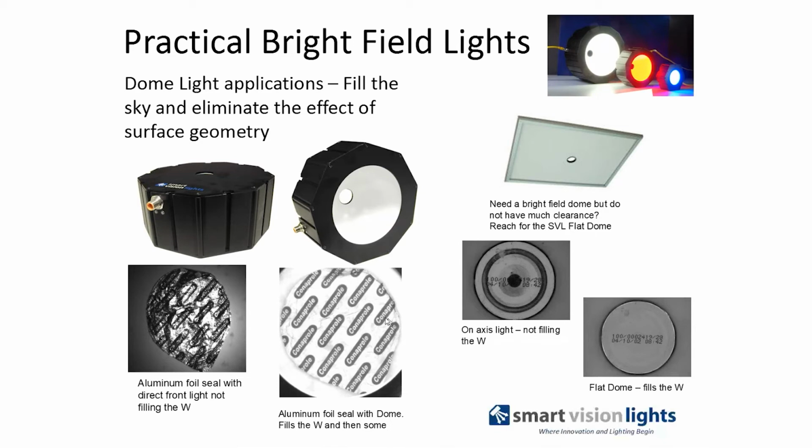And in fact, we touched upon this very subject we're talking about today in the previous module where we were talking about bright field lighting, showing that sometimes when we have surfaces like the crinkled aluminum surface of this pudding cup here, or even the shiny lid from a baby jar, you can flatten out using a dome light. This is a common solution for dealing with specular surfaces,